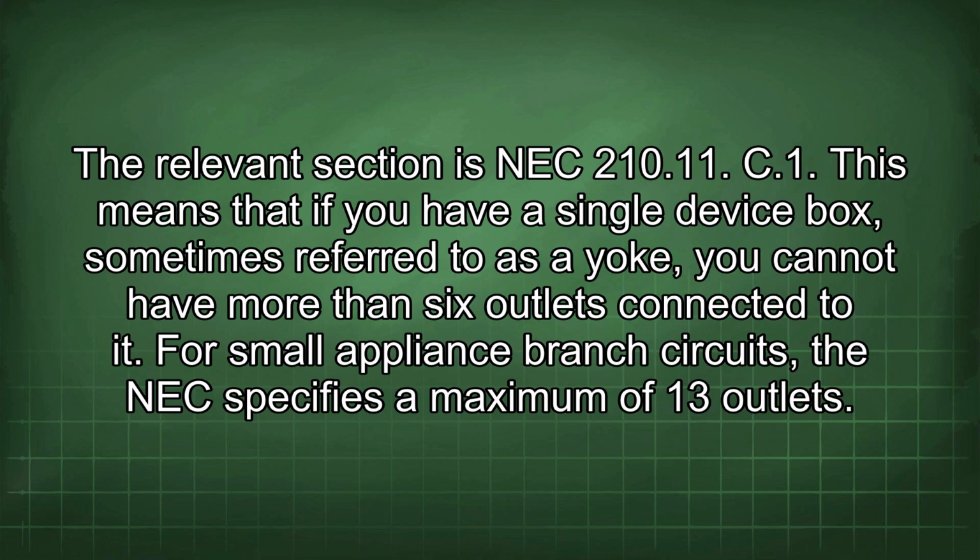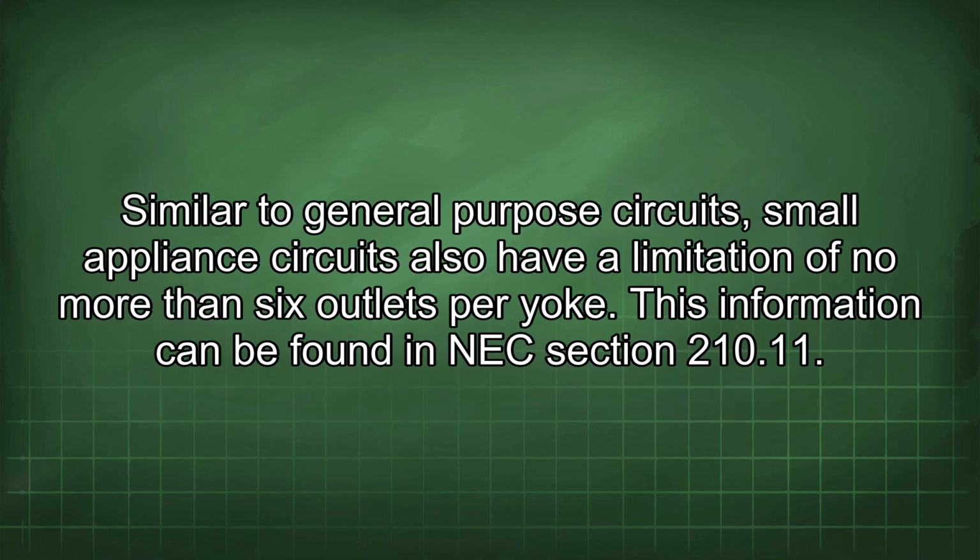For small appliance branch circuits, the NEC specifies a maximum of 13 outlets. Similar to general-purpose circuits, small appliance circuits also have a limitation of no more than 6 outlets per yoke. This information can be found in NEC section 210.11.C2.